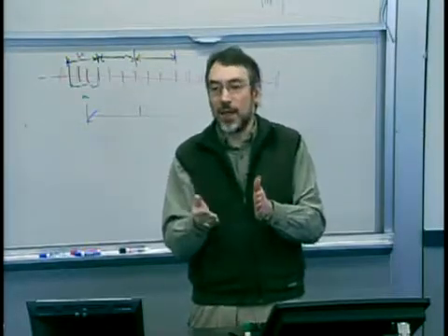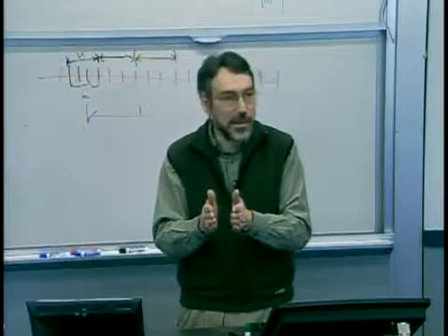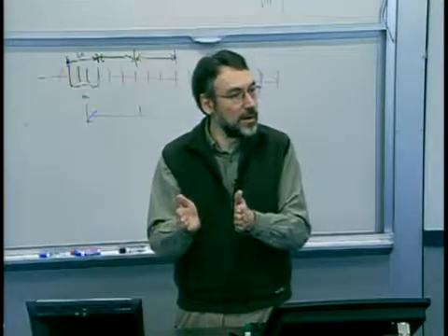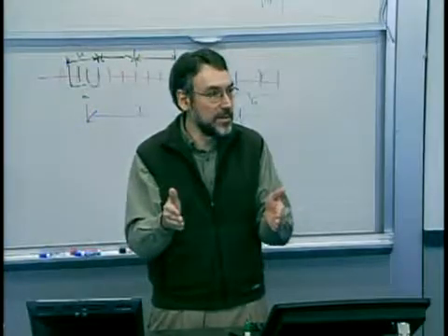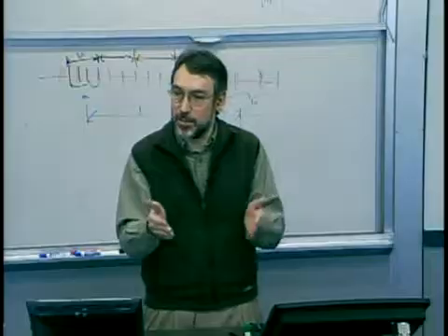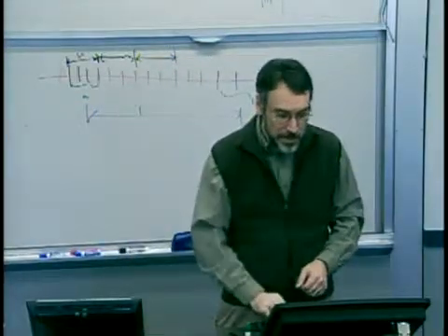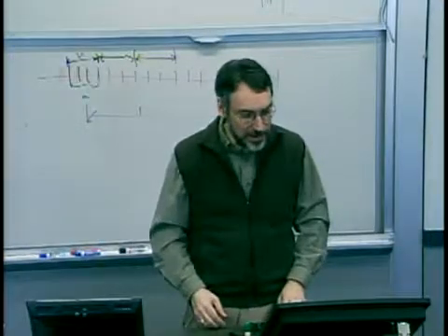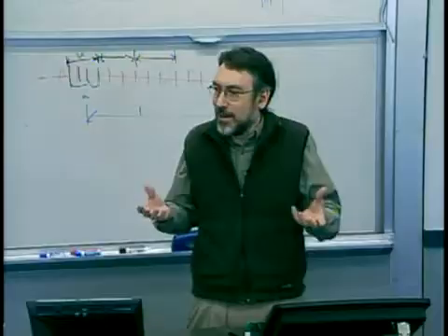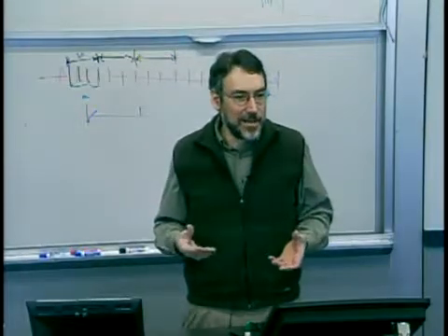It may cost a lot of energy and time to move the mean a little bit closer to the center of my spec limits. Is it worth it or not? Or would my time be better spent shrinking my variance if I were looking for possible process improvements? You can start to make those comparisons. Now, the last thing I want to do with the CP and CPK is give you a little bit of a qualitative feel for these, because what is a good value for CP and CPK?